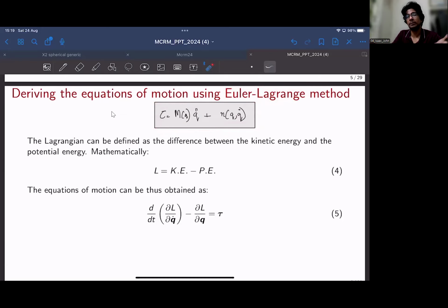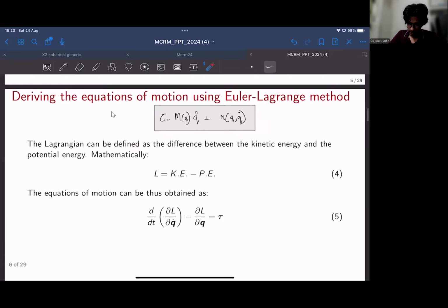Newton-Euler methods can be interpreted in many ways, depending on what frame of reference you choose to define it. But what we do is make a recursive formulation of the Newton-Euler method so that you can easily propagate the forces through the links as well as velocity from one link to the adjacent link.